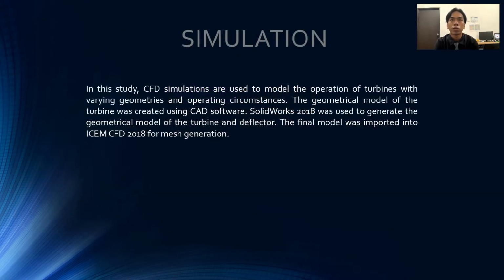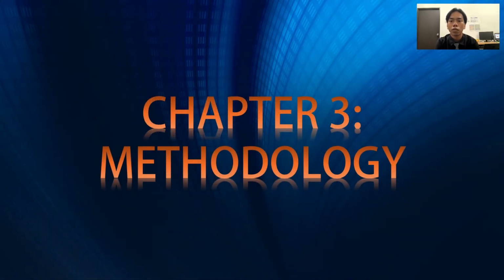Okay, for the last one, the simulation. In this study, CFD simulation is used to model the operation of turbines with varying geometries and operating circumstances. The geometrical model of the turbine was created using CAD software. SolidWorks 2018 was used to generate the geometrical model of the turbine. The final model was imported into ICEM CFD 2018 for mesh generation. That's all from chapter 2.